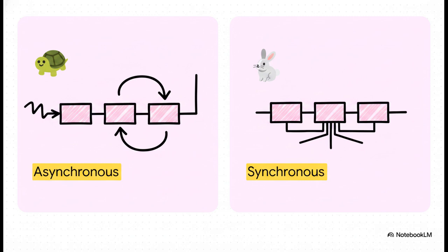This creates this cascading ripple effect, which unfortunately introduces a propagation delay. On the flip side, we have synchronous counters. Here, every single flip-flop gets clocked simultaneously by one common clock signal. Since there's no waiting for a ripple to travel down the line, synchronous counters are way faster and more reliable, even if they're a bit trickier to design.